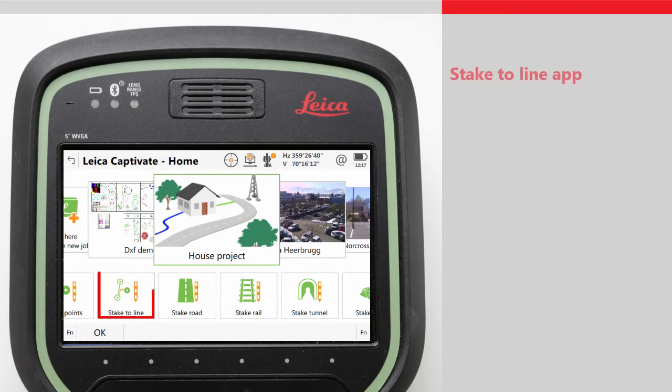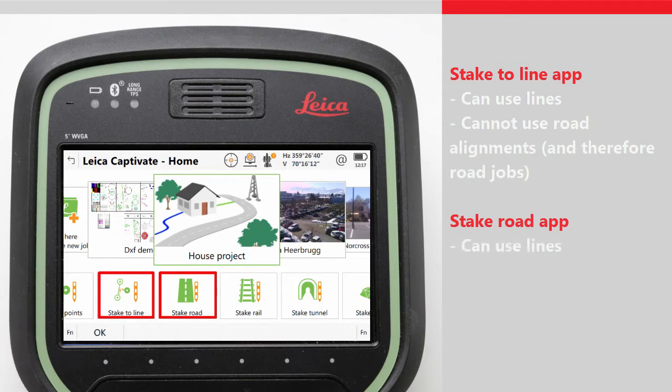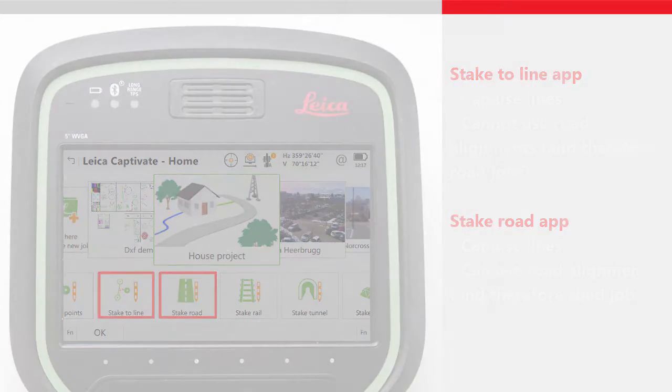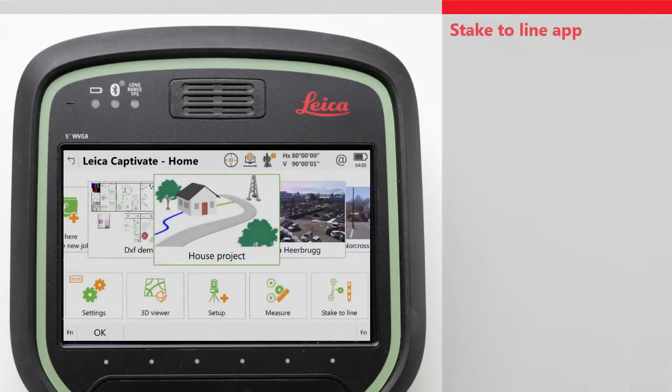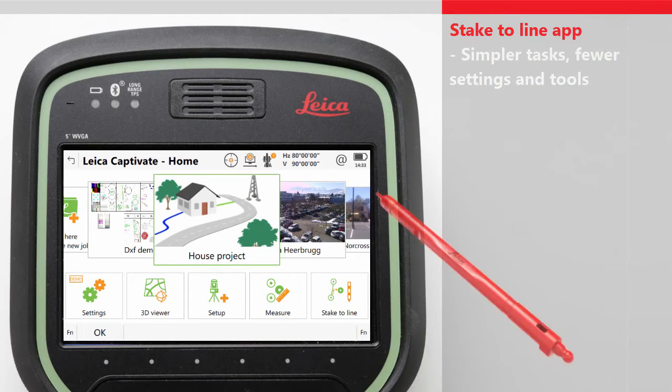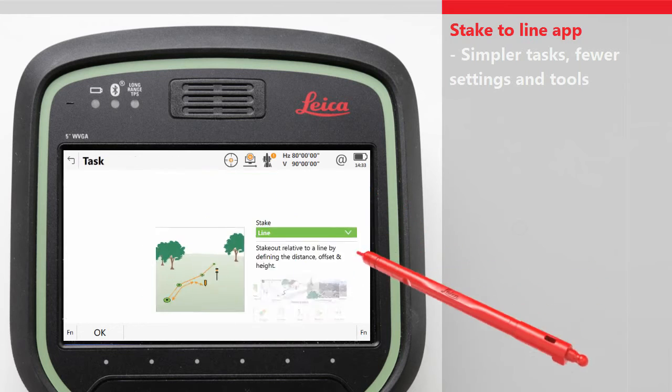Now we know a little bit more about lines and alignments, we now need to know which of these objects can be used in which apps. Basically, the Stake to Line app can only use lines and cannot use alignments, whereas the Stake Road app can use lines and also alignments from a road job. Let's now look at the second factor which defines which app to use. This is the task to be performed. The Stake to Line app allows a number of relatively simple tasks to be performed. I will only describe a few of the tasks and the basics here. Other videos will give more detail.